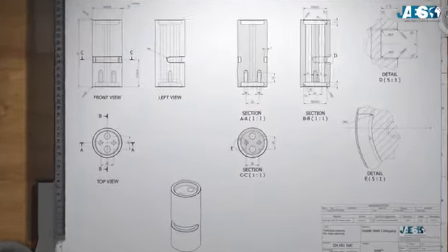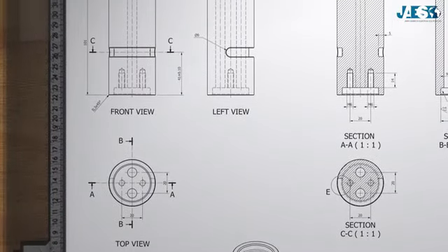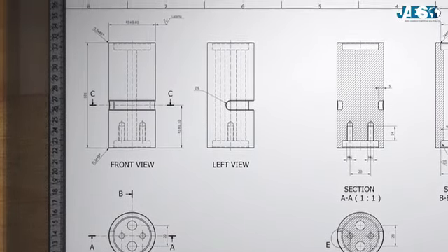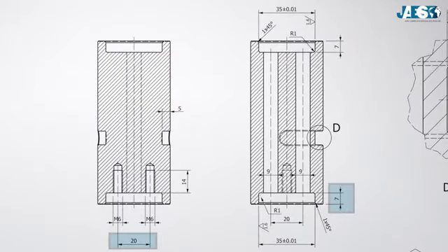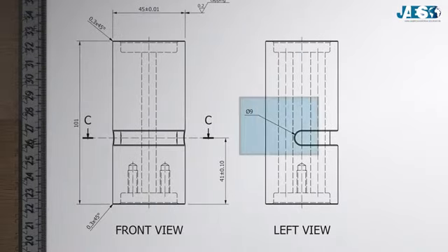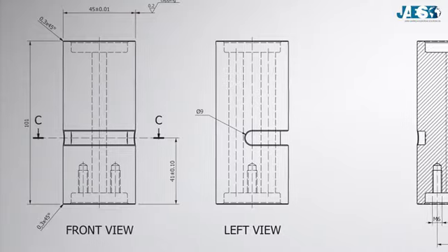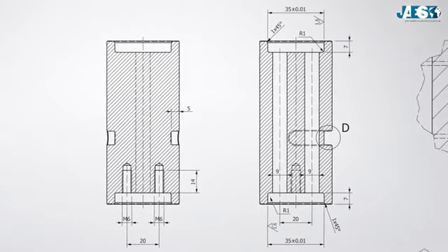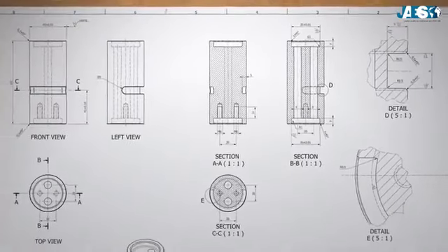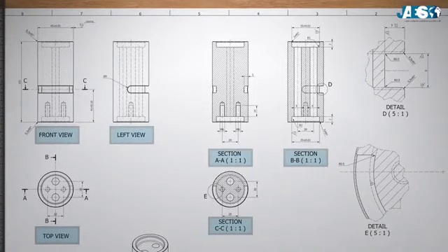Dimensionings, on the other hand, are represented through thin, continuous lines, which placed side by side with numerical values, can indicate lengths of the various parts of the object, fillets if the letter R is present, diameters if the symbol phi is present, chamfers by specifying the height and degree of inclination. They should always be arranged externally in relation to the projection and can be attached to visible lines and axes of symmetry. Therefore, they are placed internally only if necessary, and hidden lines are not dimensioned. For these reasons, there exist other views and sections.